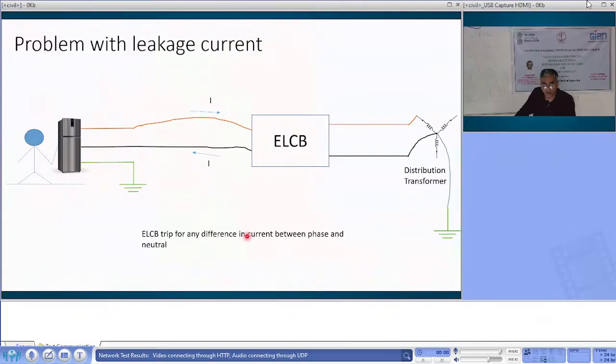In summer days in Nagpur we have the coolers that we are operating. So we have many news reports that because of electrocution, that shock, several people die. Either they don't have a proper grounding system, and there may not be a ground connection. There may be only 2 phases that you are using. So always the chances of leakages are there because of the old coolers, damage of insulation is always a chance. So for safe operation, you always have the ground and it works.